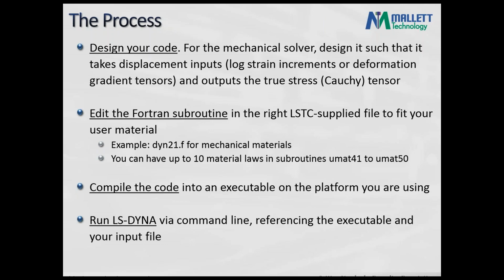Now that you have your code designed and your pseudocode ready to write, you need to edit the Fortran subroutine, which comes with those LSTC files that you downloaded from them. In that specific file for your mechanical materials, you're able to use up to 10 different material laws. They have 10 slots for that, so you can have a wide range of custom materials in your simulation. Then compile the code.